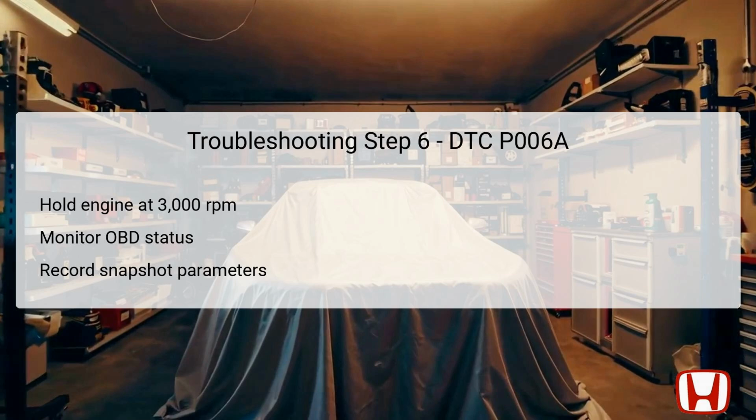If it shows as failed, replacing the MAF sensor or IAT sensor 1 is necessary. However, if the status indicates passed, consider checking for loose terminals or other connection issues, and try to replicate the failure by monitoring similar driving conditions.